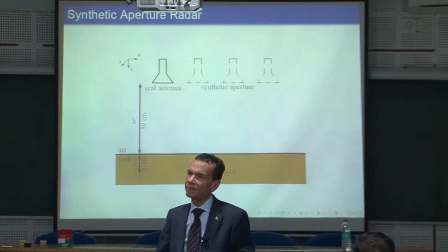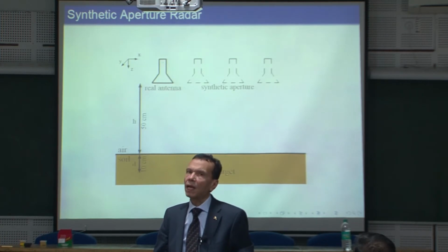The question was a little different. If you are working at a lower frequency where we are using a coax system, not really a waveguide system, then we can do a calibration on the coax plane. And we don't have a distinct plane in the antenna where we can do a calibration. If it is a horn, it's very easy. I understand that. Suppose we had a nice looping antenna there, I don't have a distinct aperture on which I can do a calibration.